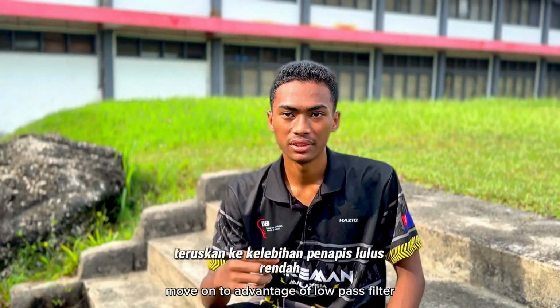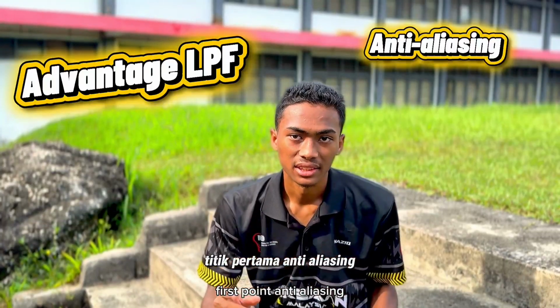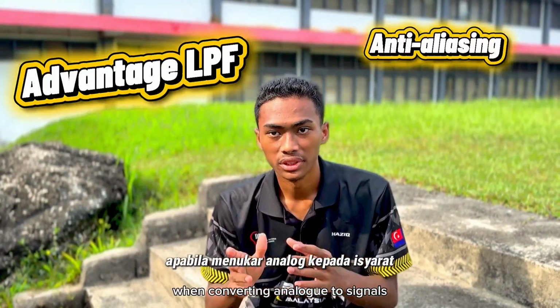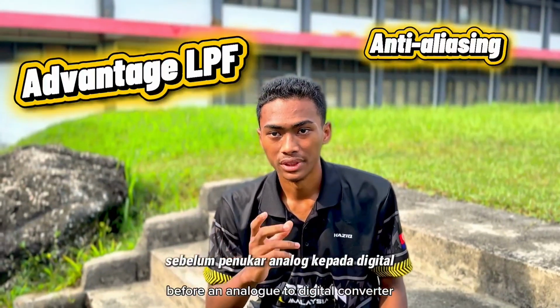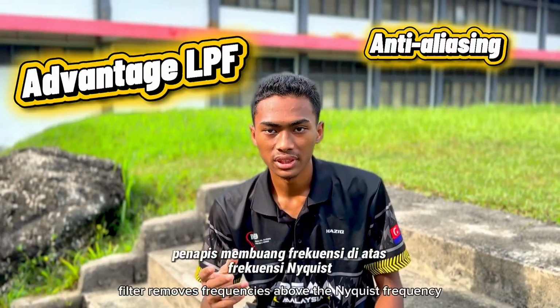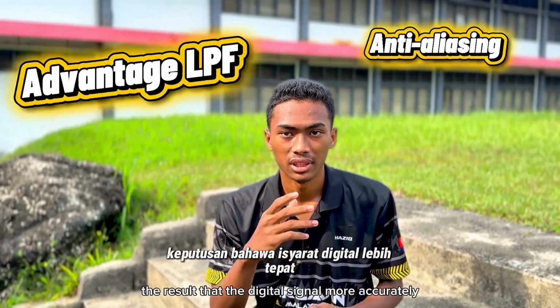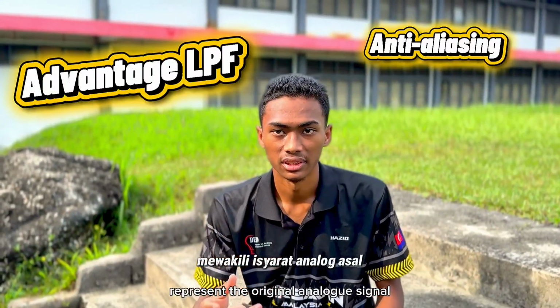Move on to advantages of low pass filter. First point, anti-aliasing. Anti-aliasing prevents errors when converting analog signals into digital signals. Before an analog to digital converter, ADC, samples the signal, the low pass filter removes frequencies above the required frequency. The result is that the digital signal more accurately represents the original analog signal.